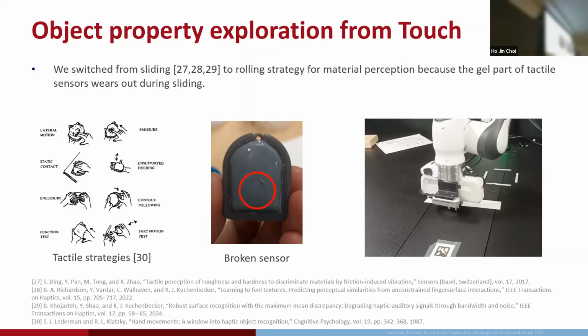I think what all these methods are trying to do is interpolation of the data points that it has, and doing some optimization based on the observations. And Gaussian splatting, I guess, is a good way to represent the surface of the object also. But the reason why I chose the GP is that, first of all, it gives the distance function, which I believe is useful for robotic control scenarios. And then the other reason was that it is easier to incorporate the tactile information.